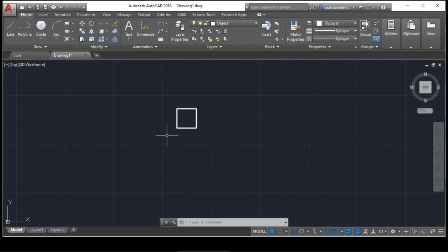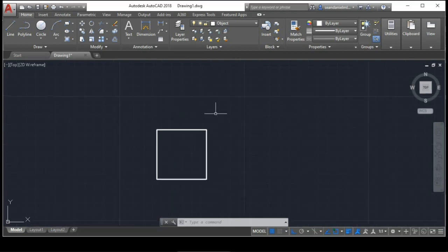Now what if I'd like to draw 3D objects? When drawing 3D in 2-dimensional space, the general rule is to use 30 degrees for 3D objects. I'll show you what I mean. I can create a line from this point over here, specify the unit to 1, and the angle to be 30 degrees. As you can see, the line was 30 degrees in reference to this line. That is because AutoCAD uses a default feature for angles, which goes in a counterclockwise mode. 0 degrees is on the right side, 360 degrees towards the left.